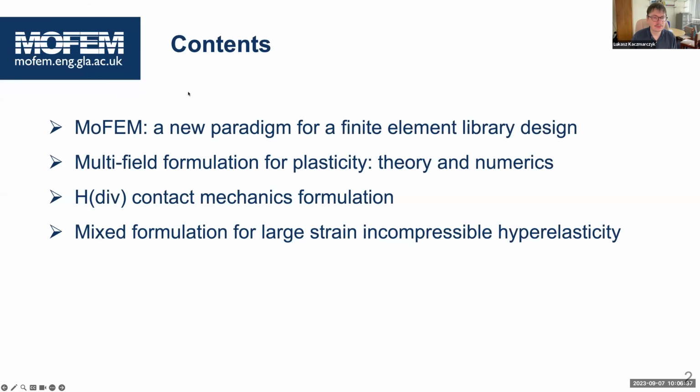Okay, so today I will be talking about MoFEM a little bit, multi-field formulation for plasticity, why we're doing that, H-div contact formulation, and mixed formulation for large strains applied to incompressible hyperelasticity.